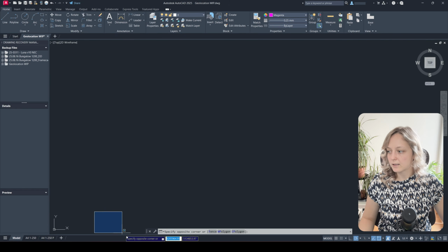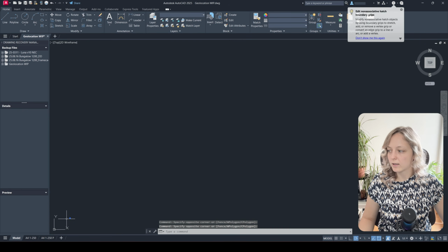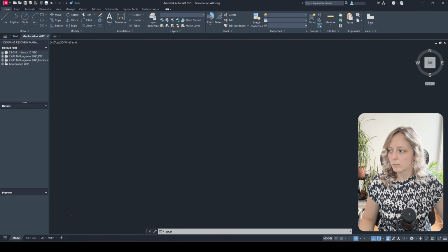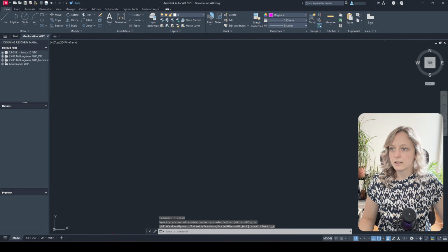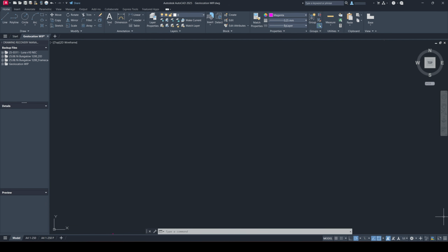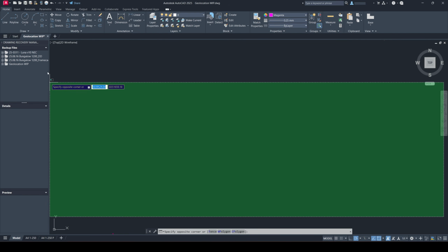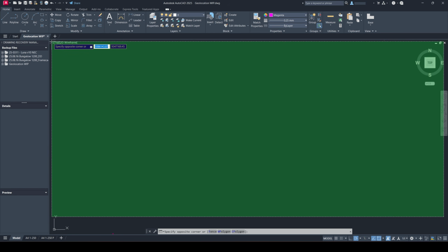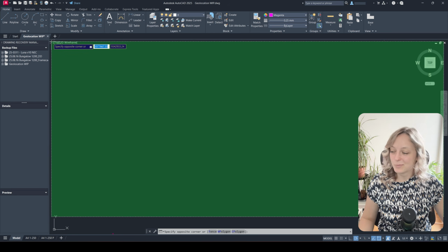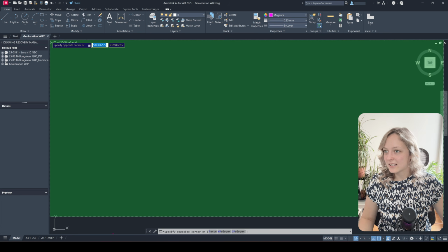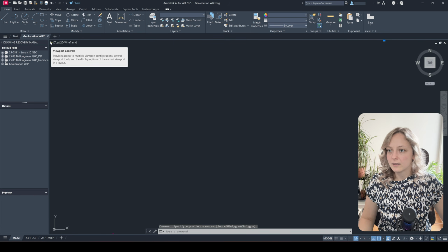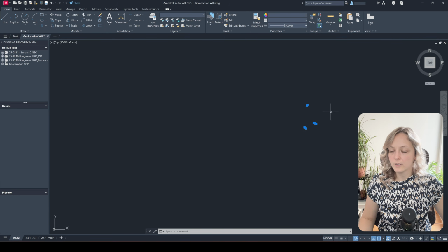I can still see the smudge a little bit below. It keeps moving away because the file is too big, and this smudge is my project. But when I zoom extents, I can't see anything. What I do in these cases is take my selection and select everything that is outside of my smudge, meaning the actual file. I select everything, and now I can see that something is selected here, and this is probably the culprit.